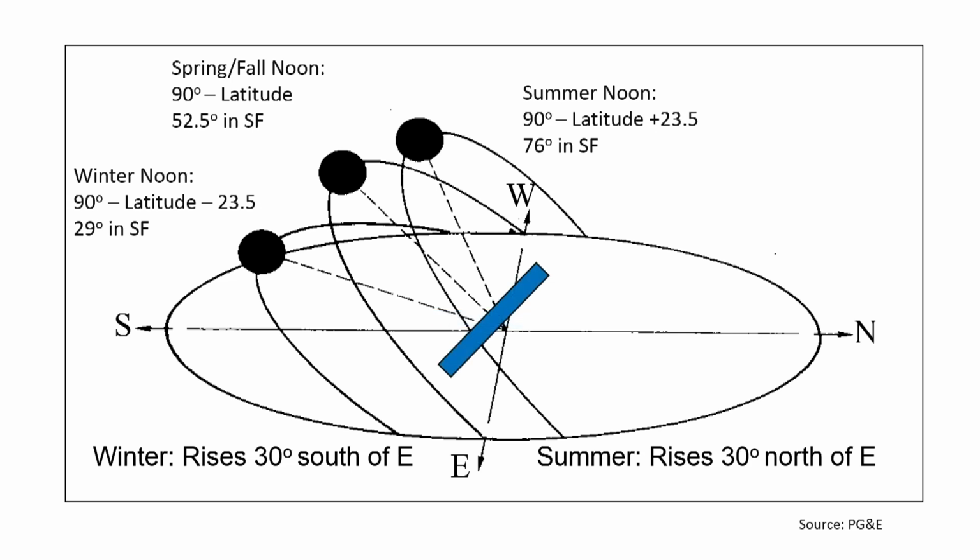So what they say is, if you tilt your panels to your latitude, you're going to get the most average sunlight exposure throughout the year. If you were to tilt them back and catch more of the summer sun, that might be a strategy to maximize your sun in the summer when your utility rates might be higher. There are strategies there, but I'm just talking about the physics. So how you tilt the modules is going to determine how much they produce.